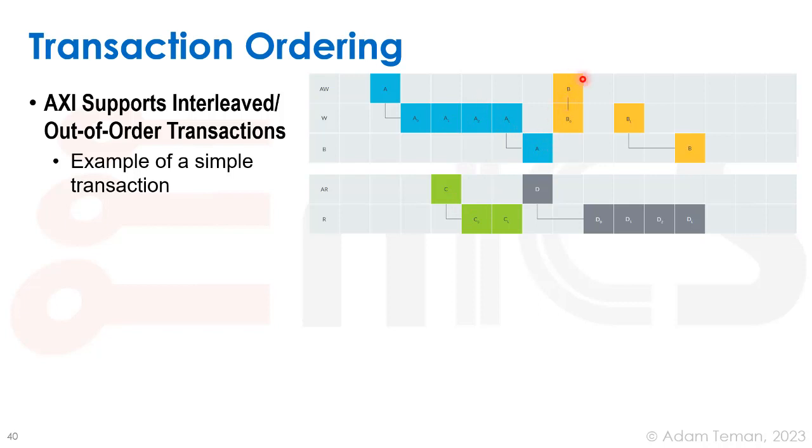Again, we can have the second write transaction done over here. We could provide the write address and the write data at the same time. They didn't have to be delayed from each other. We could have some wait states in between and not provide all the write data one after the other. The actual acknowledgement by the slave could also be delayed. And at the same time, we could again have another outstanding read transaction happening. So this is interleaving data.